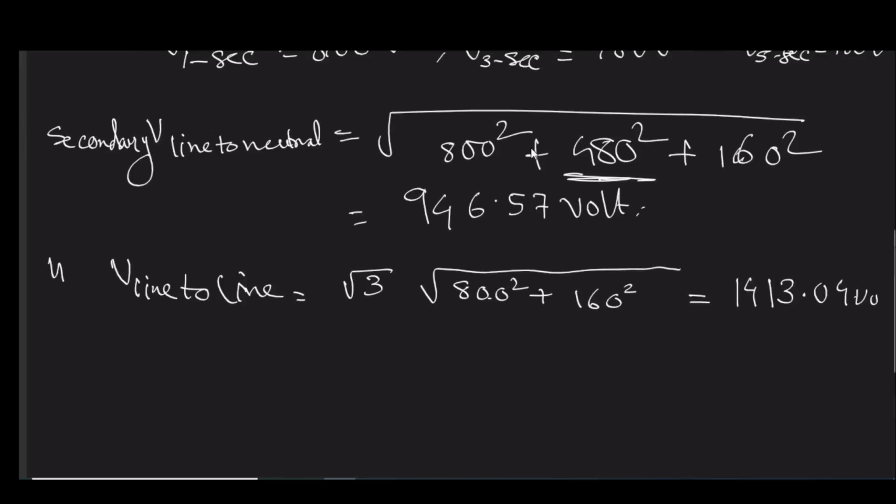So now you must have understood the concept of oscillating neutral. Although you may say, sir, it is line and neutral, means line and phase, they are also in proportion. Obviously, if you find out this ratio, you will get a constant proportion. But what is the catch here is that your phase voltage is considering zero sequence component that is continuously rotating at 3 times the fundamental frequency. So here you will have an oscillating neutral.